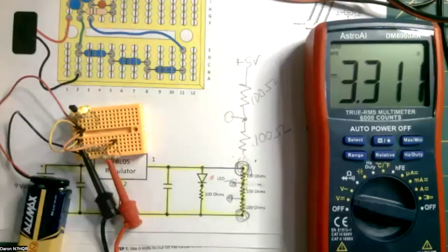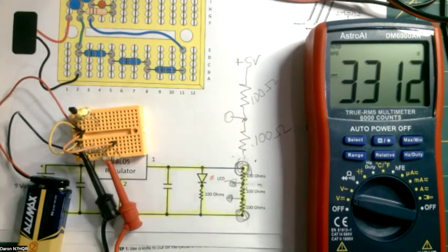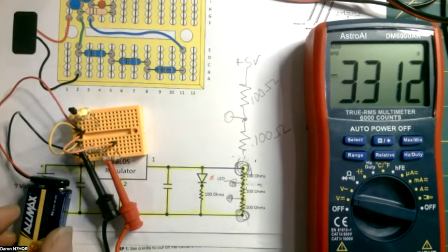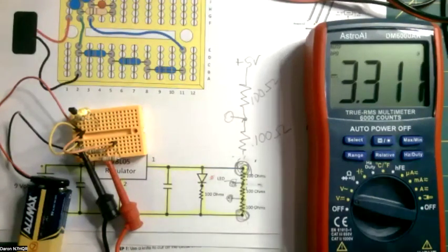But with the digital multimeters today, it's typically 10 million ohms. And so it has very little effect on the circuit normally. Although you can get into some real high resistance areas where it might have a little bit of an effect, but typically not. So anyway, we can break this down and move to parallel.